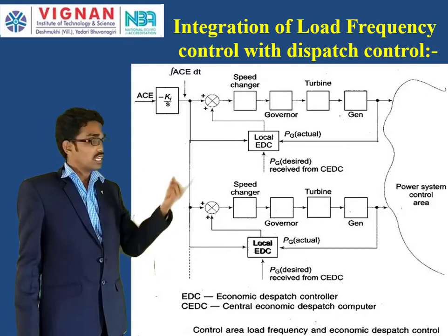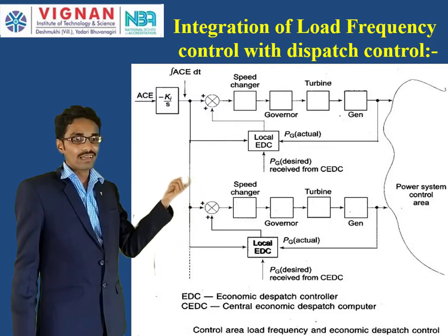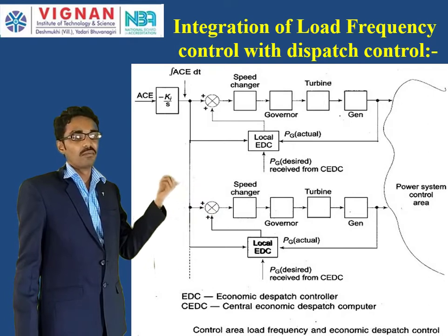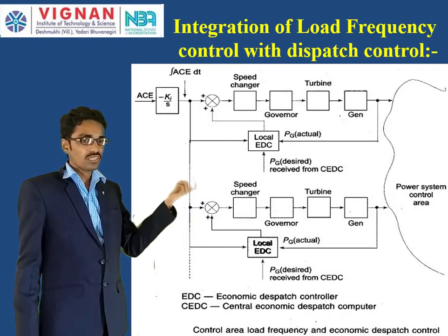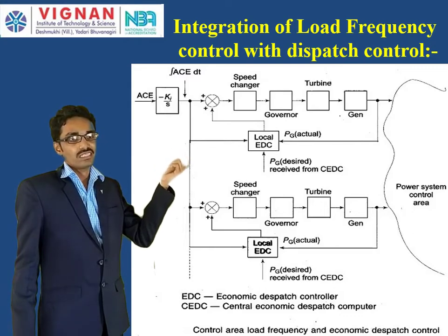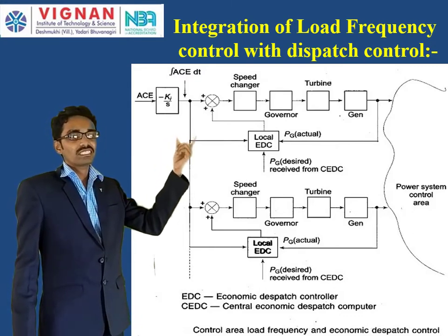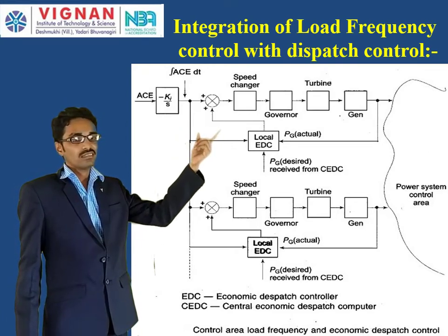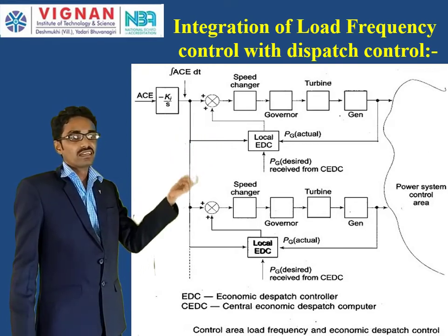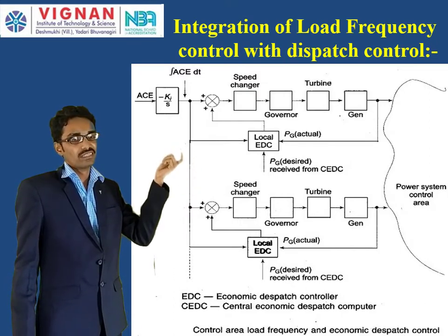What happens is, if there is a change in the power demand, it is going to get the signal as a power generation command. Here you need to increase the power generation. There is an actual value and a difference value. The actual value of the power generated is coming from the generator, and the reference value is where you need to increase the power generated.